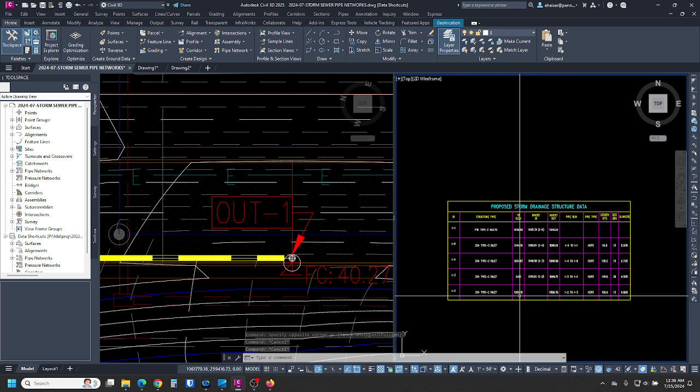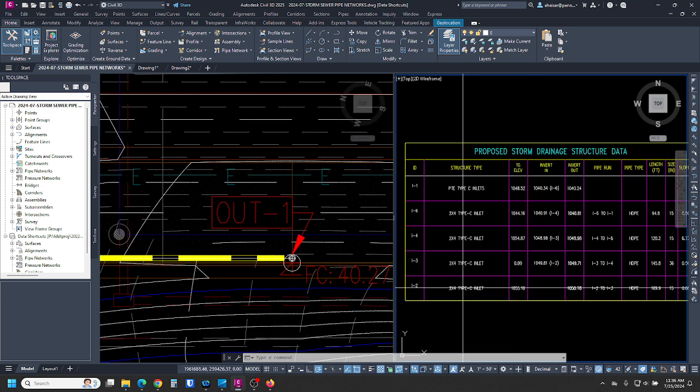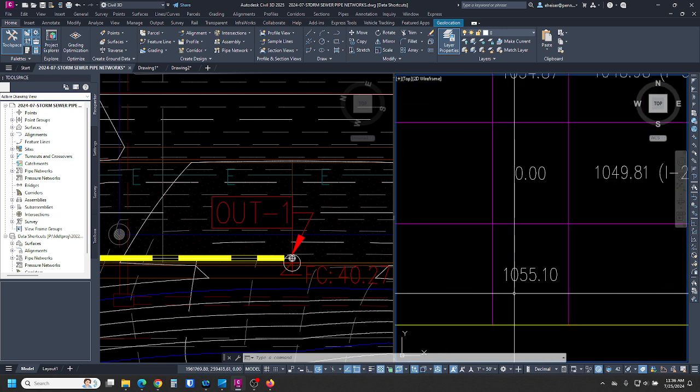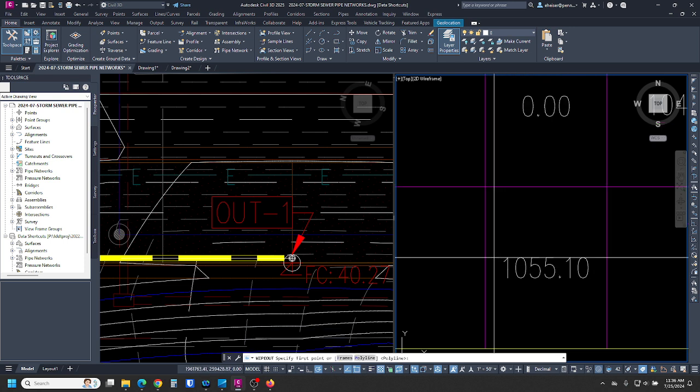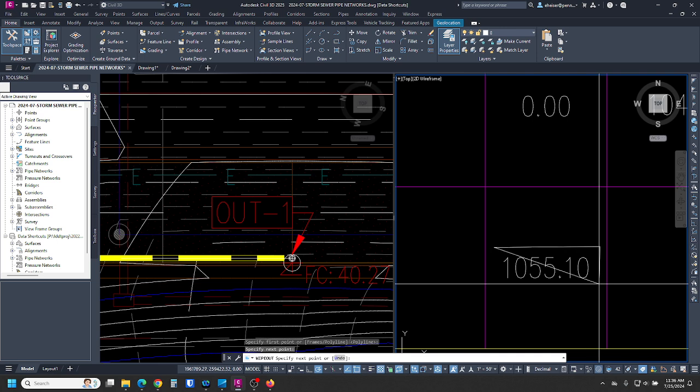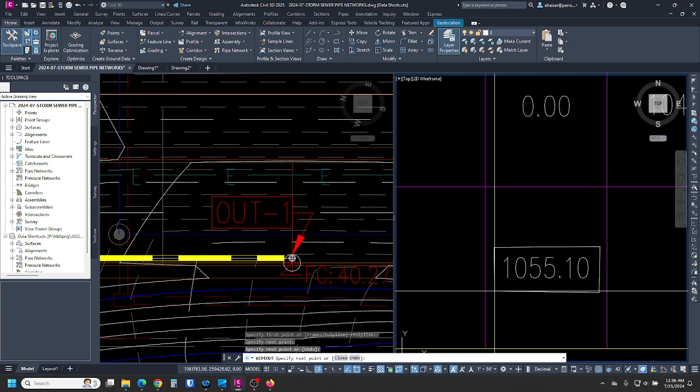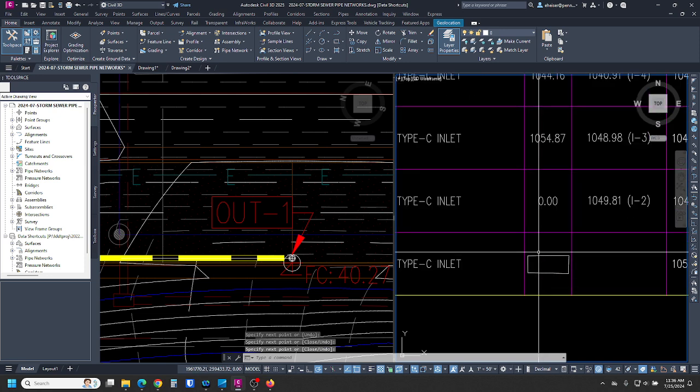And then hopefully in the future, we can figure out a way to take that variable out for those types of structures. But the way you typically do that, we're going to pretend that this I2 is actually an outfall pipe or an end wall or the end of a culvert. We're just going to type wipeout. And we're going to use a polyline, so I'm just going to draw a box around it. Wipes it out so you can't see it.